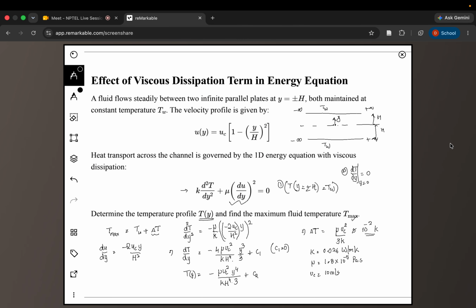So from here forward, in most of the equations, when we say energy equation, we usually neglect this viscous dissipation term. However, we'll also see some problems where you have, say, engine oil or something which has very high viscosity. In those particular cases, this term will become significant, and without it, the physical significance itself would be gone. So this becomes important in some scenarios, because you see the maximum temperature happens somewhere away from the walls.